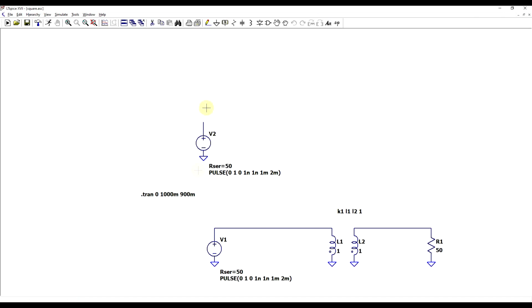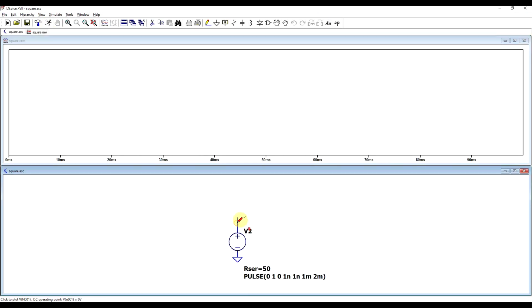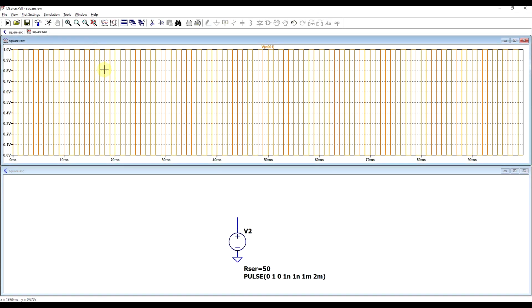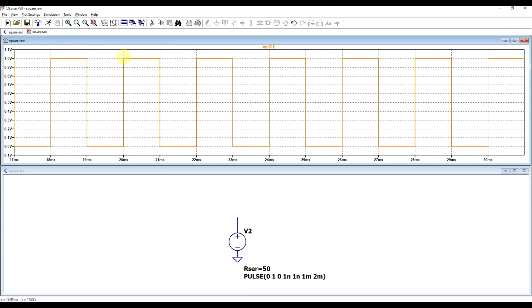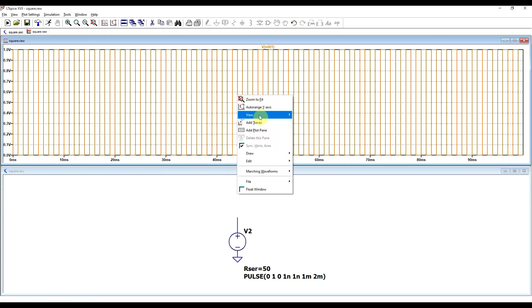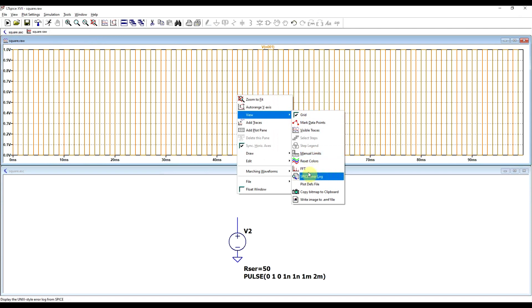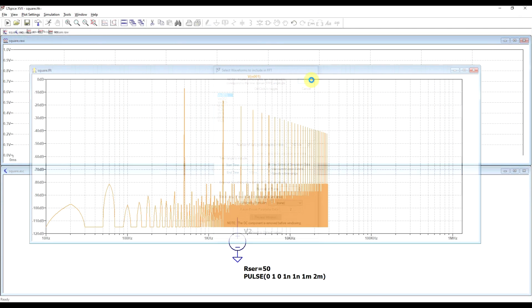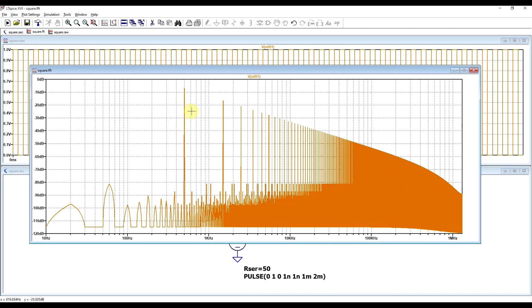So what I prepared here is, first off, a signal source, which is outputting a square wave. If we just zoom in a bit, we can see that this is a 500 Hz square wave with a 1 volt amplitude. Now we can analyze its spectral content by looking at an FFT spectrum of this signal. We can see that this signal is formed from a fundamental frequency at 500 Hz and then various upper frequency multiples.